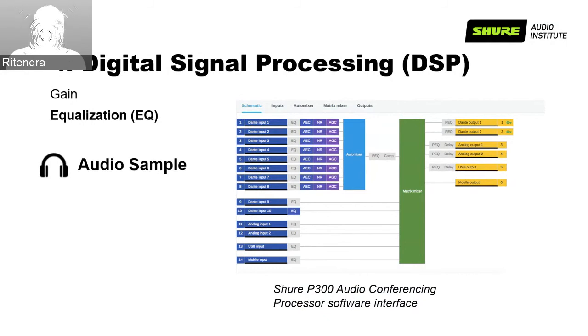For example, if your room is noisy, first cut the low end and high end. And then if you feel like the audio is not clear, you can play with adjusting the low end or mid-high. Mid-high is mostly recommended because that's more on the intelligible frequency range of the human voice, right? The human voice mainly resides between 200 to 8,000 hertz with a speech clarity around 1K to 5K. EQ is effective for reducing low-end HVAC, mechanical vibration, and high-end HVAC air noise.